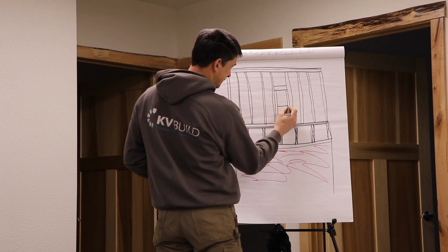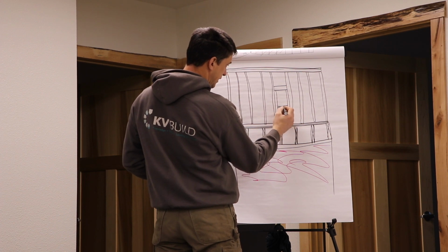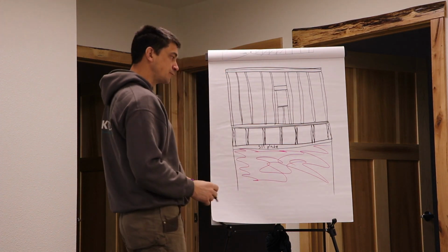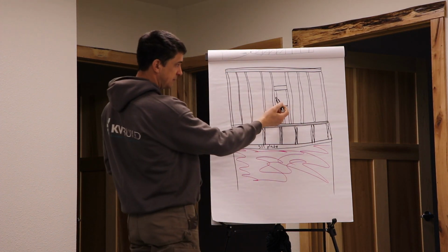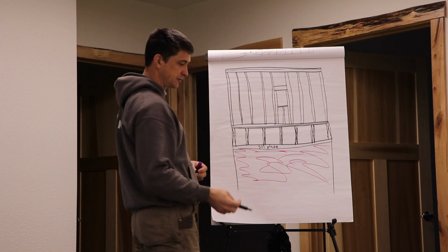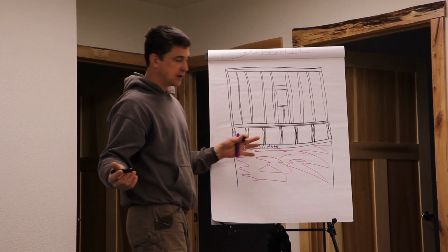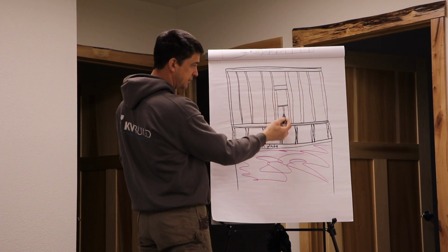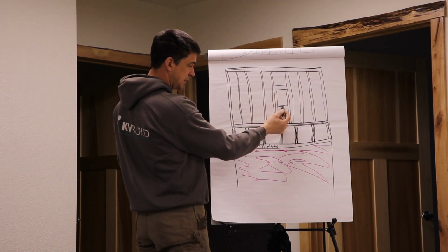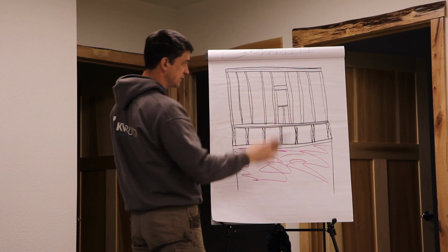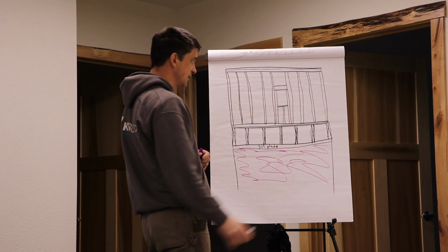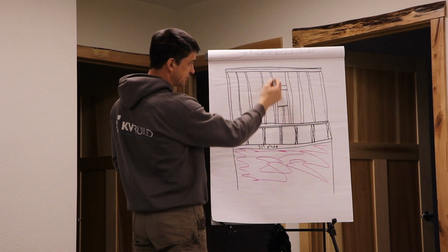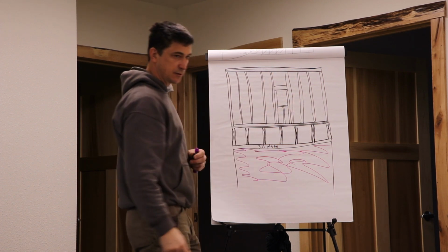Then we would have a sill to the window, and if we had any other studs underneath, then we get these here. I like to call them a shoulder stud because it is a very logical term to me. The other name for them is a cripple. These under the sill, our jack studs. This, if it's running full length next to an opening, is a king stud. Okay?